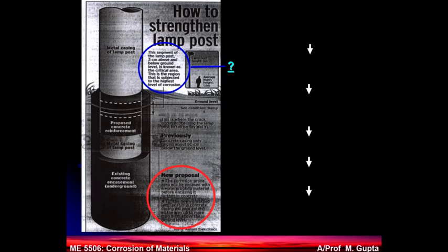What is the flow related corrosion you can expect? Cavitation? Not really. It's not very turbulent. Erosion? Not really. It's only water. Impingement? There are only three. So that's how you should narrow down depending on the situation and catch it.